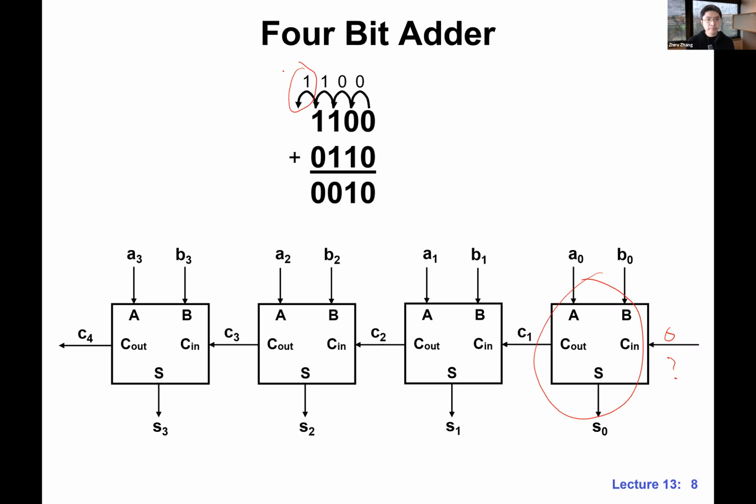Okay. So this is the 4-bit adder. All we are doing is cascading these 1-bit full adders altogether. That's where we have the so-called ripple carry adder. But one more time, let's look at the delay. We just agreed that each full adder takes 2 nanoseconds. What is the critical path here? What is the longest path?